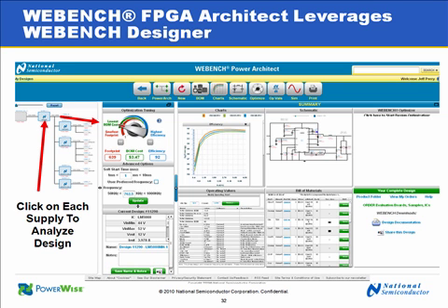We call that a project, and that's a collection of all the power supply designs in your design. So here we have 5 different power supply designs. On the left side, we've got the system block diagram. As you click again on each one of those blocks, it will pull up the WEBENCH design on the right side, and you can use the normal WEBENCH simulation, bill of materials management, and build it steps to optimize your design.